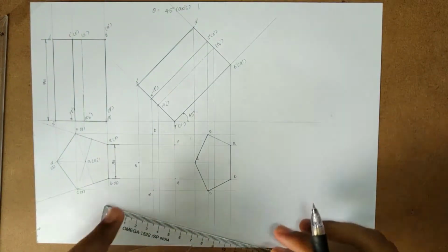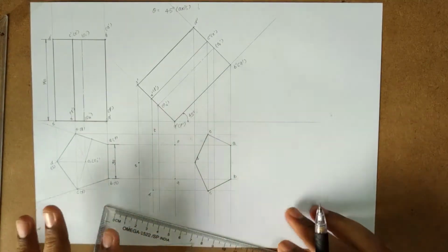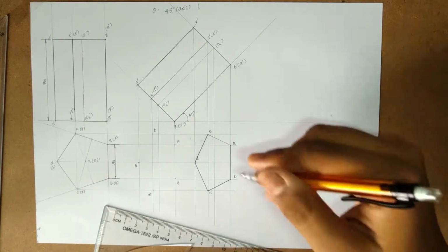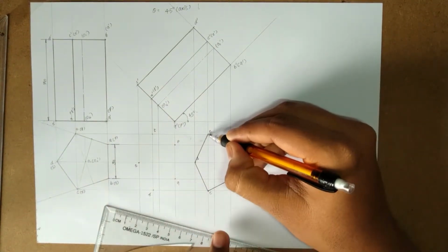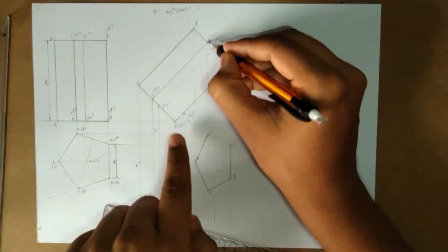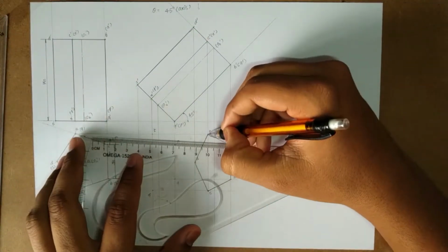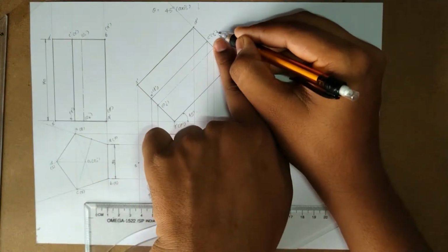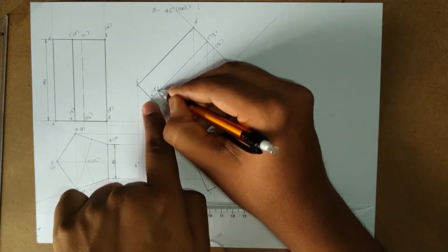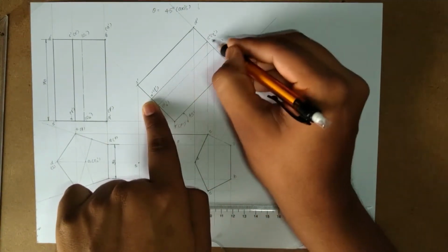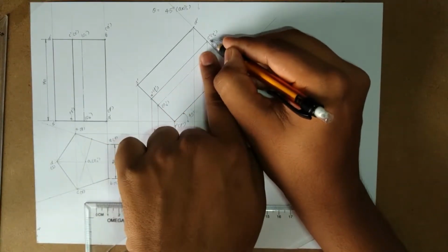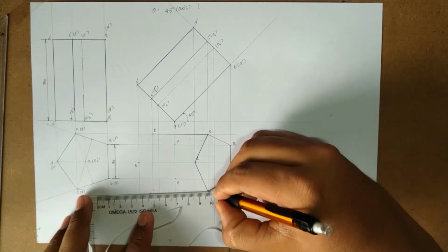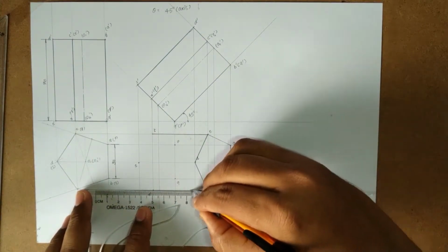Okay, so here we have to remember one thing: the outer portions will all be visible, the inner portions will be invisible. So how do we check outer portion and inner portion? First we check the connection: which is the outermost point? It is point E. So which is the connecting line from point E? T. So from here we will connect a line from E to T. Verify that point E dash is invisible over here, and this is the connecting line. Once again we need to check the invisible point only. E dash to T dash, it is a line. From C dash the connecting line will be R dash. In the same way, from C dash the connecting line is R dash. So this is our outer part.